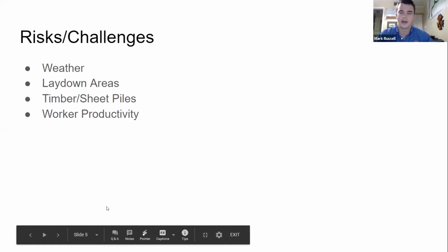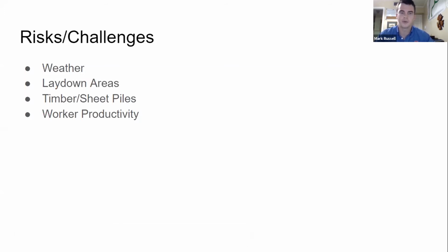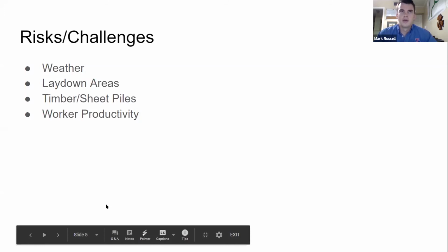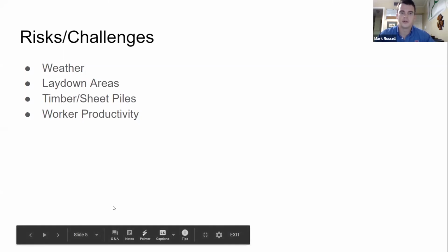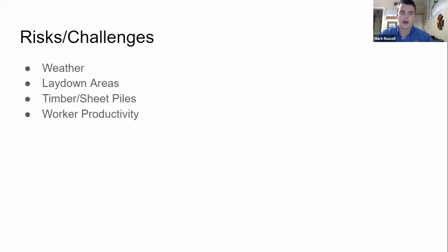And then our laydown areas. We weren't sure that the laydown area at Wharf A was going to be big enough. So we are using Bow Brothers Marine Yard, which is 8.5 miles away, but it does have good highway access, which keeps the girder trucks moving. We're staging the girders and the barges there. And then the timber piles and some small tools like welding machines and concrete tools, we're staging at Wharf A.